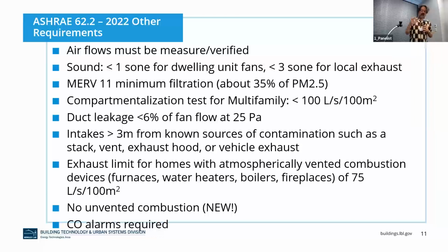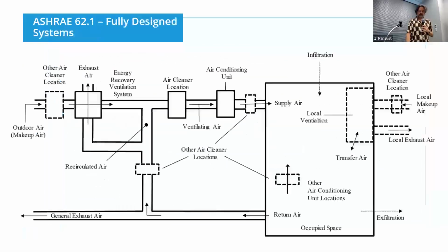And then a few odd things at the very end here that you might consider to be safety requirements rather than air quality per se, things like requiring carbon monoxide alarms. Hopefully we never get carbon monoxide in a home, but it can happen, particularly in homes that burn fossil fuels inside them. Speaking of which, after an 8-year struggle, we finally do not allow what we call unvented combustion. That is things that are burning natural gas or propane or whatever fuel it is and not vented to outside. We do not allow that anymore.